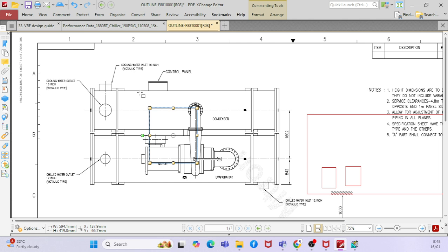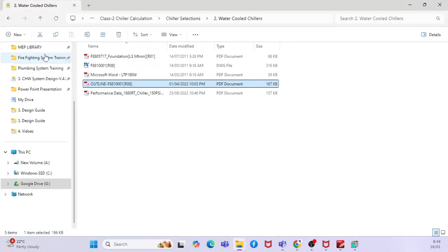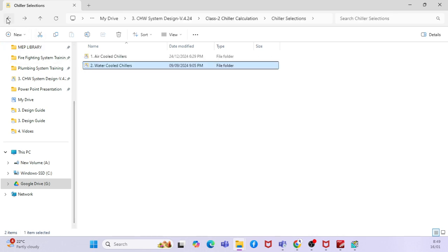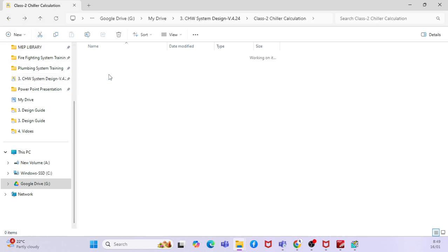What I was trying to say was, the cooling water that comes back to the condenser, is its temperature similar to the chilled water, or is it higher or lower? That's what I was confused about. No, it will be higher. The cooling water will be higher, I will say like 42 or something like that. Also, I can open one of the schematic diagrams for your reference. This is one of my previous projects.